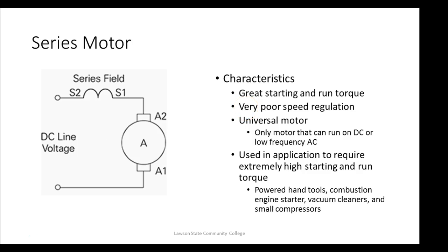This is a series motor. Now what happens here is that when we start this thing up, that series field is very few windings because it's in series. Your rotor is sitting here not turning, or the armature is not turning, so it almost has zero resistance, right? The only thing it's got is the resistance of the wire. So what happens is you start out with an extremely strong field in both these, which means it creates a what? Creates a lot of torque. A lot of torque.